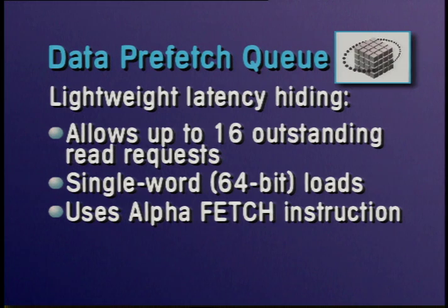by executing a fetch instruction, which is an Alpha opcode meant to be used as a prefetch hint to a board-level secondary cache. In T3D, a fetch causes a single word load to be initiated from memory, possibly remote, but since the destination is not the processor, the fetch can be acknowledged as soon as we've latched the address, and the processor can continue with other work. When the load response returns, it's placed in a slot in the prefetch queue that was reserved for it at the time the fetch issued.